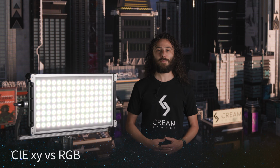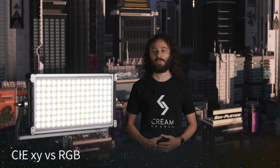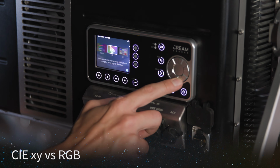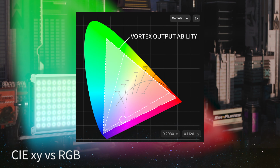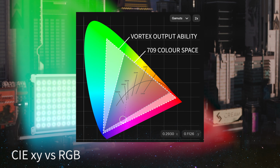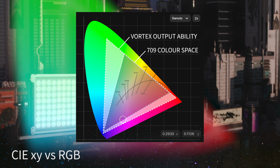When it comes to color, the Vortex offers a wide variety of control modes: CCT, RGBW, HSI, just to name a few. And since every manufacturer uses different red, green, and blue chips, things really get interesting when we start discussing CIE XY modes. These control modes operate natively within the fixture's gamut, meaning you don't have to worry about managing color spaces as you would have to with RGB color modes.